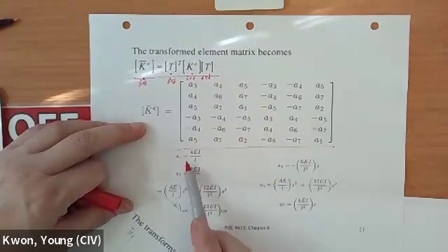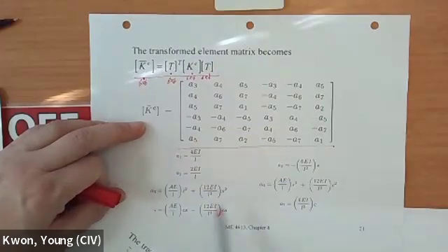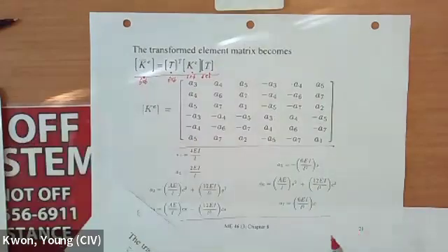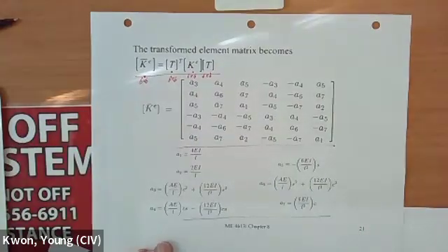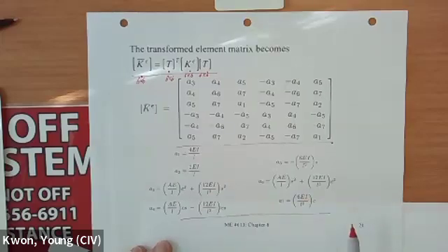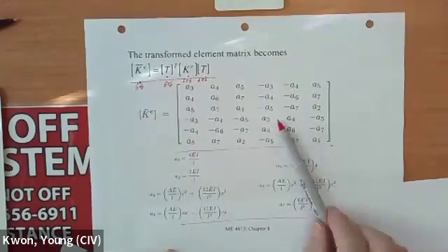So this expression, A1, A2, A3, A4, is shown in here. So a little more complex, but not very difficult. This indicates how much contribution there is between the axial component and the bending component, because of the orientation. So that's kind of coupled between the axial force and the bending moment in here. So anyhow, this is going to be a 6 by 6 matrix.